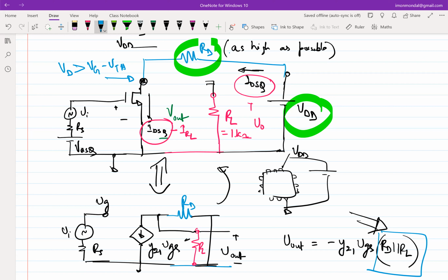If VD is lower than what you expected, then you raise VDD, and automatically the drain voltage will go up. Fine. So as far as the biasing picture is concerned, we can do this. But what is the root cause of RD loading the quiescent picture? The root cause is that the voltage at these two nodes, that is VDQ, and the voltage across RL are not the same before we connect them.